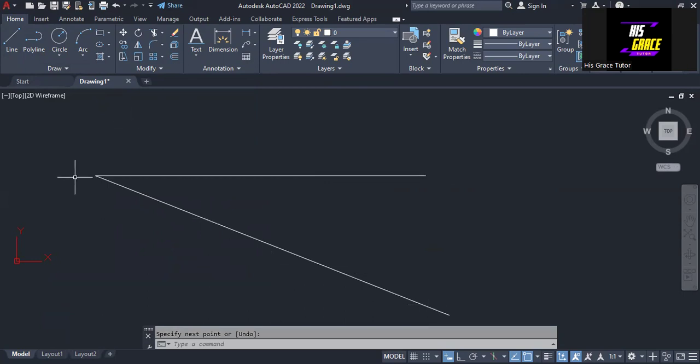So I'm going to label each end of the lines. Okay, so select single line text. Then the height of the letter is 2, and the rotation angle is 0. So I'm coming to this point. This point, label it as point X. This point, I will label as point Y, and this is point Z of the line. Okay, so we have it like this.